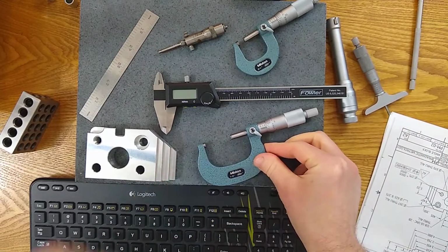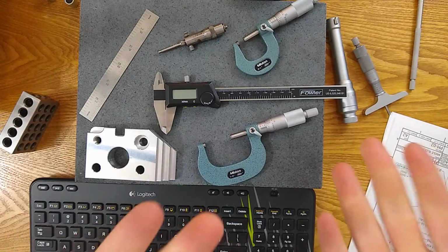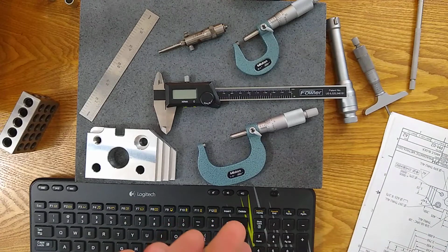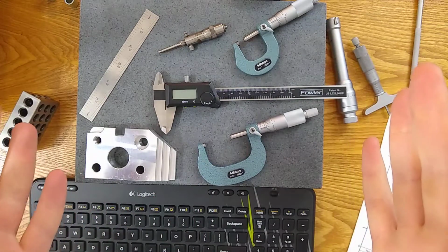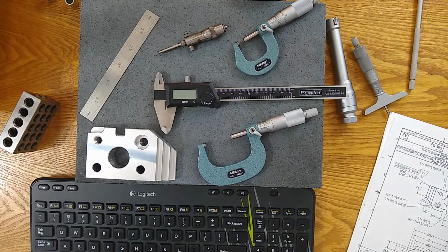Number two, what tools do I have available that are accurate enough for the tolerance zone? I just sort of started that discussion. So consider the uncertainty ratio, the 10-to-1 rule of thumb. Both of those will help guide your decision, which basically says you need a gauge accurate enough for the tolerance zone. And what is accurate enough?